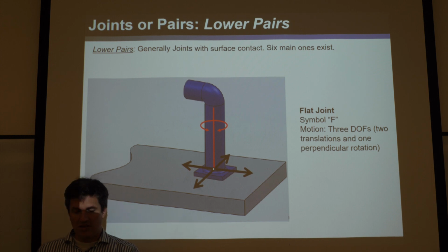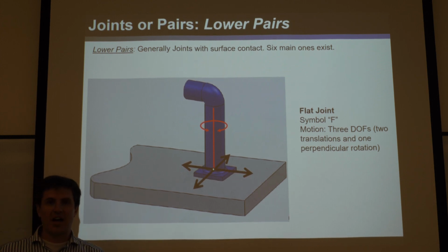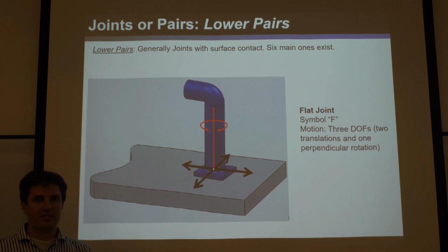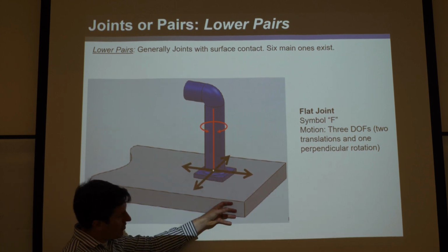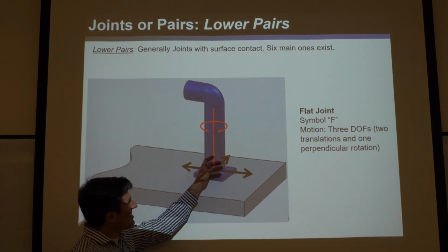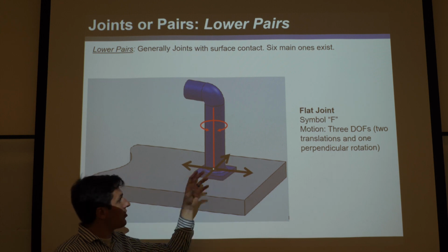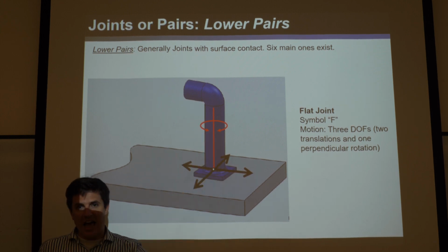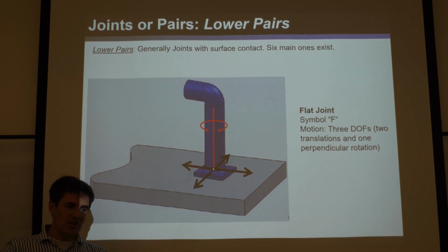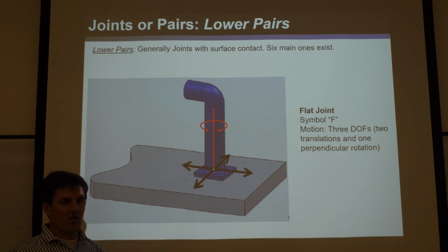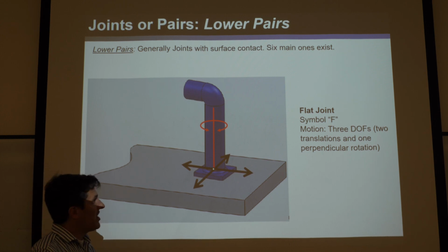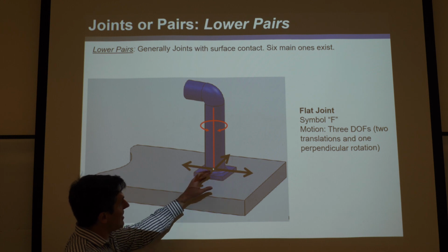And that's a rule that I want to ingrain in your mind: you can't break joints. Not only can they not go through each other, obviously, but you can't lift it off. Of course, in the physical world, you could lift it off, but you're not allowed to. Once you separate the 2 links, it's no longer a joint. So when you're analyzing its degrees of freedom, you have to assume it can't be broken.